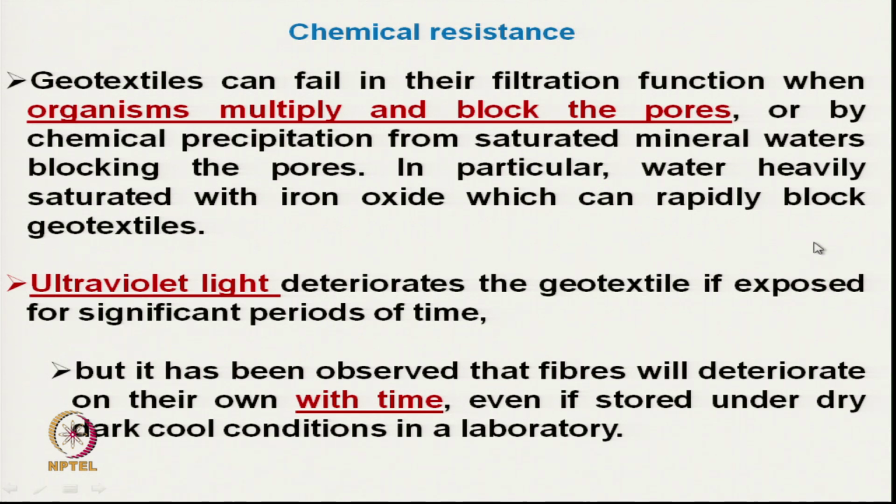UV rays also deteriorate, so we should be careful when we use geotextile in exposed condition. It has also been observed that even if we store geotextile in dark cool condition, it may sometimes deteriorate with time.